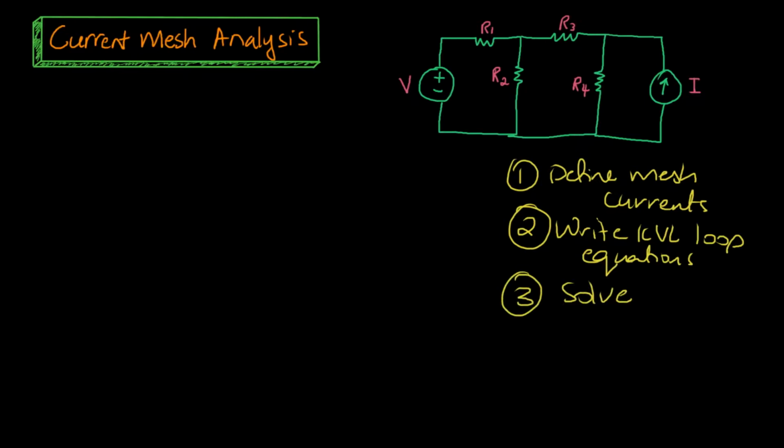Before we start any electric circuit analysis question, the first thing we need to do is set a reference node. A reference node is essentially ground in our circuit, and if it's not set for you, you can choose anywhere on the circuit to place the reference node. As a rule of thumb, in a circuit that looks similar to these, place it at the bottom here, as most textbook questions are set up for this to be the easiest way.